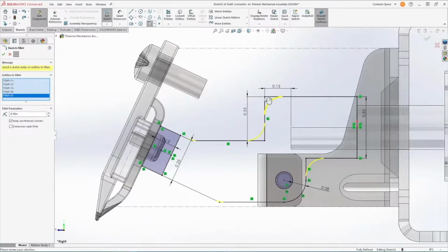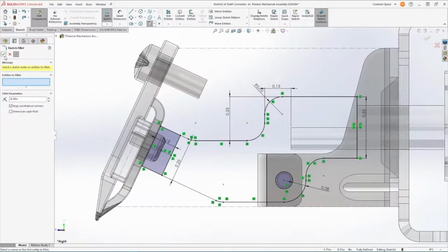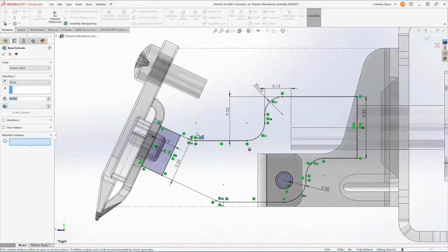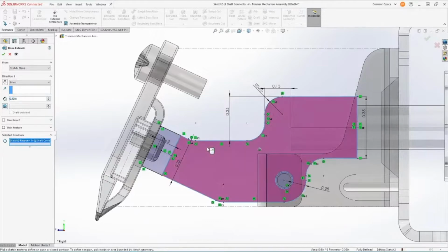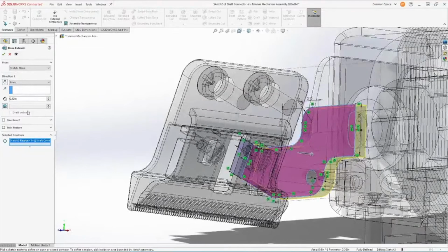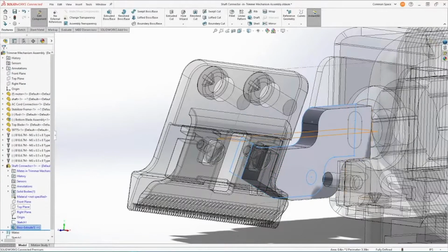Now all the fun is in bringing it from 2D to 3D. So I'm going to use an extrude feature. I'm not going to choose a mid-plane extrude or anything fancy because I'm simply going to model half of this component instead. I'm going to add some detail to this half so then I can just mirror the other half without having to duplicate any of my efforts. This is a great tip for design intent in general. You don't waste time modeling the whole thing, you just model half and mirror the other half.